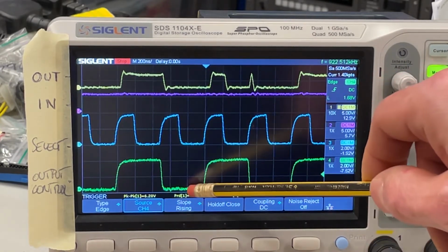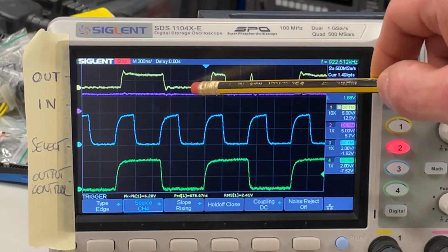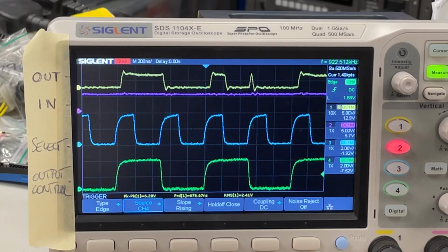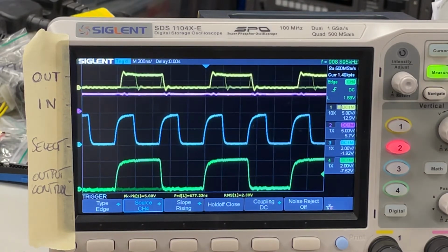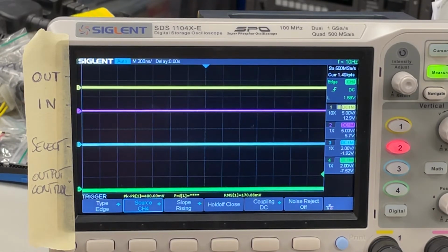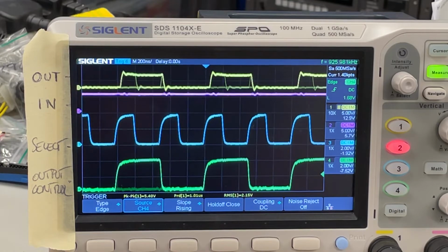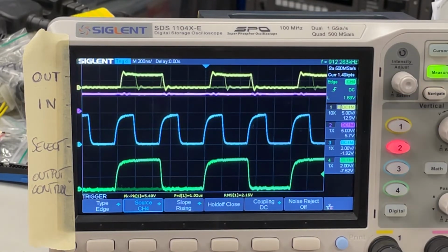Here we go. Low, input high, output low. So this seems to be working fine. Just one thing, the input is always high. If I run this, you can see that input is actually always high, regardless what happens. Let me try and reboot the 64, see if it ever gets any different. Nope, it's always high. So it seems to be working, but that line is stuck high, which I'll keep in mind.